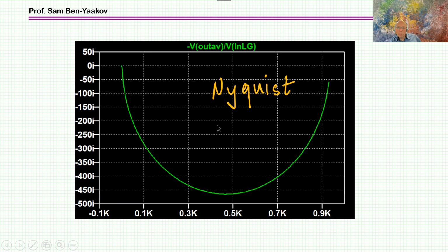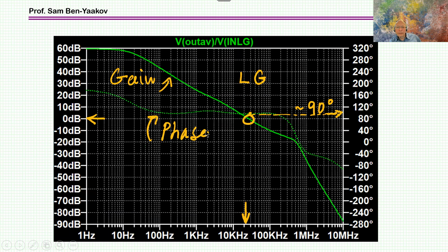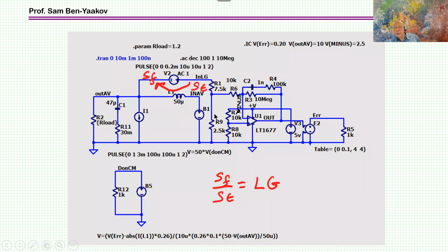So before that, let me just say something about the compensator. The compensator has a reference here. This is coming from the 5-volt divider, 2.5 volt here, the 1-to-1. And then there's a gain between here. This is dropping the voltage to about 2.5, okay? And then we have the gain here. This is the resistor, this is the capacitor, this is the input resistor.